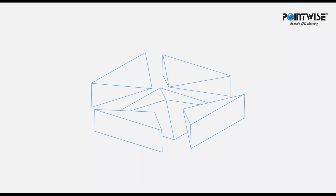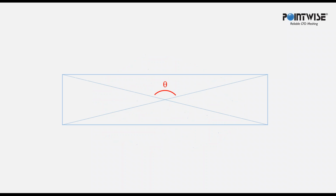Here's where the problem can come in. That angle right there can get kind of large if you have any sort of stretching on the surface, such as this. So here's a higher aspect ratio quad. There's some stretching in this quad. We're looking at the same angle, theta, and you can see how it can get pretty large, and it's going to get larger the higher that aspect ratio.